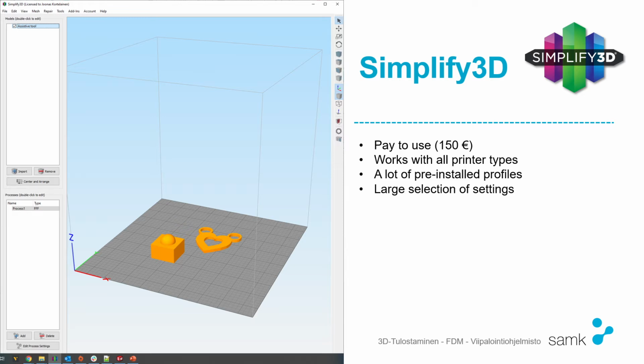And this was one of the few software that had the possibility to put 10 to 20 objects on the build plate of the printer. Well, every software can do that, but here you could adjust each of their parameters. So you could set that the first 5 cubes will be full cubes, so their infill percentages will be 100%. And the next 5 will be 10%, and so on and so on. You could select these settings for each and every model that is on the build plate.